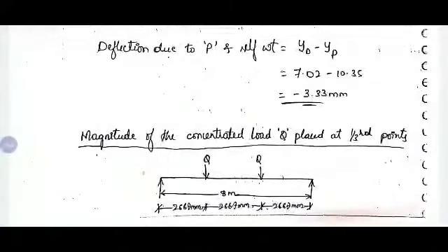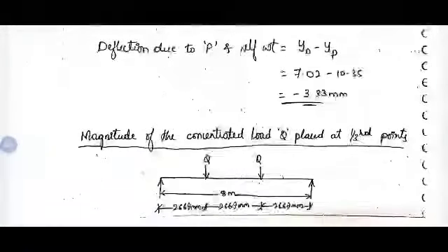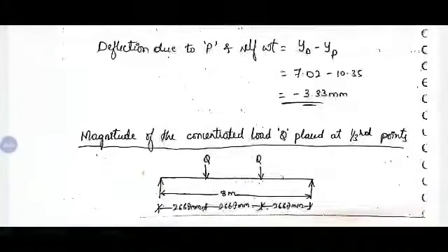Then in the third question, what you need to calculate is the live load. It is not given, but the condition is given that you are applying the live load at the third points. So when you divide the given beam into 3 equal parts, at the center 2 points you are going to apply the point loads, but we don't know what load is applied.